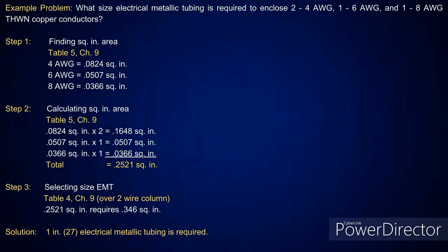Sure. And if you look, when we started designing the wiring methods, it's funny because when I was doing box fill, it was based on what? Same size conductors or different size conductors? When I get over here to the conduits, what is it? Same size or different size conductors? You just got to know where to go get the information. And that's why I say if I'm doing boxes, you should get to where you know this.